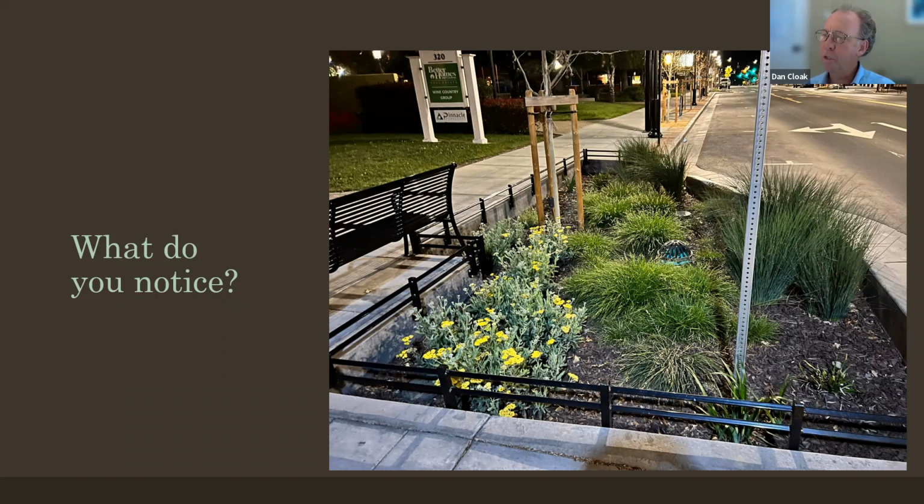The key with success in bioretention facilities seems to be, if you can avoid it, not to have this be a well with sides all the way around, but have a way that the roots can extend at least in some places out into other soils.